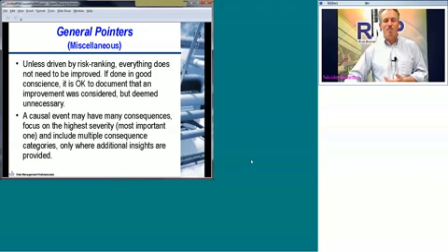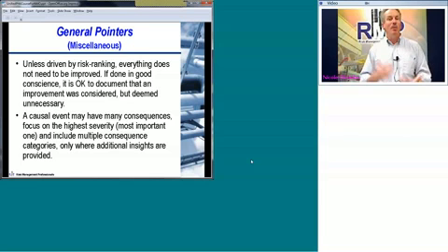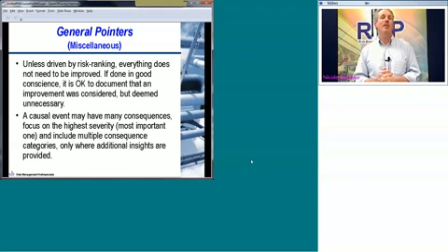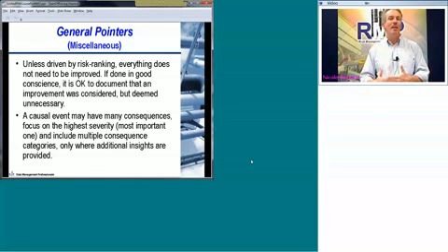And also, a specific causal event may have a bunch of consequences, but you really want to focus on the ones that are most important. That valve failing open that we talked about earlier, it could have a severe safety impact and also a bunch of other problems with respect to business interruptions, replacing equipment, and whatever. Well, go ahead and list those if the team is discussing them, but focus on the overpressure event, focus on the thing that's going to be a safety impact and is driving your risk ranking, and that's the part that uncovers the weaknesses. You don't necessarily need to break it into categories for every consequence. And we'll be talking a lot more about that in Module 12.